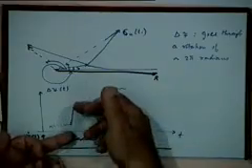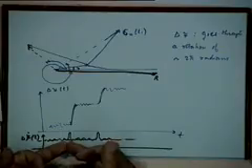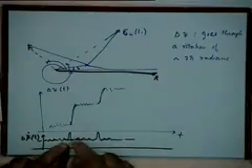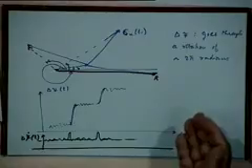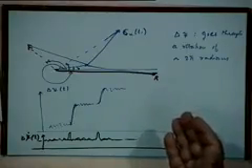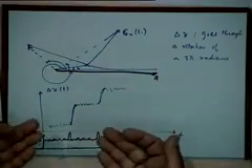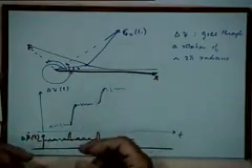If you look at the spectrum of these, the spectrum of the unit step function or the spectrum of this pulse, right? Most of the spectrum is concentrated at low frequencies. So there is a significant energy of these pulses or these jumps which lies within the bandwidth of your message signal, and you will not be able to eliminate that, right? And this suddenly increases, right, because of the increased occurrence of these pulses. As long as the noise amplitude is small compared to the average carrier power, the occurrence of these pulses is very, very infrequent, right?